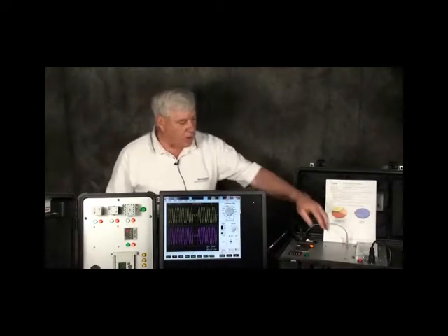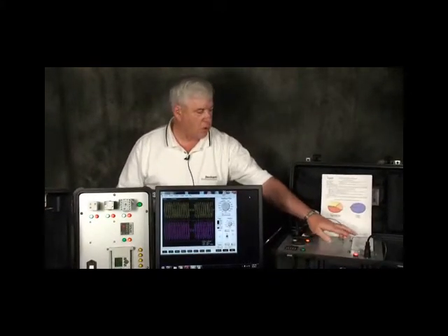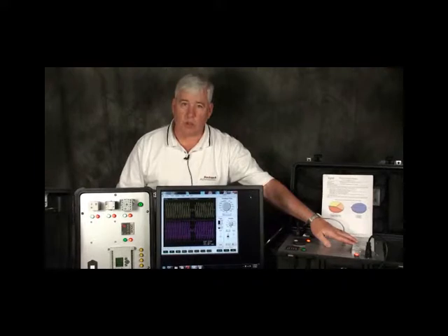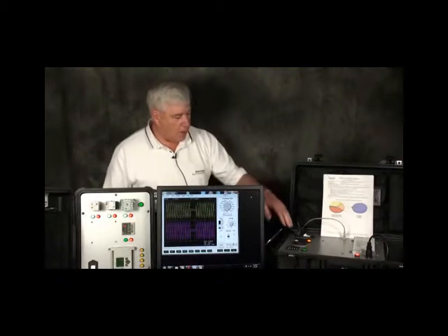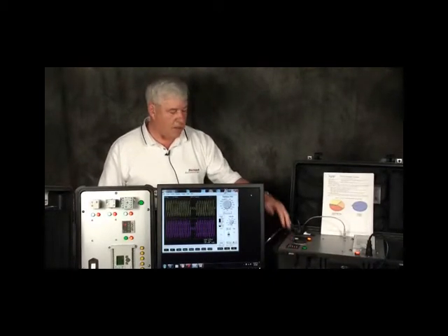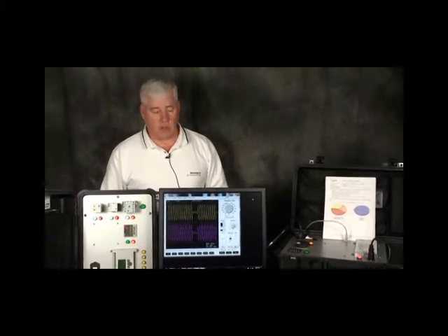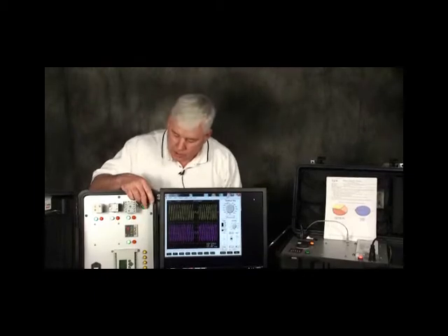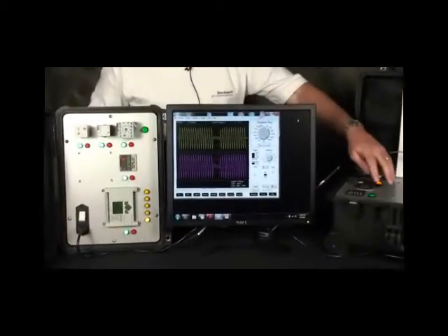So now we're back to our demonstration, and what I'm going to do is put in series with the load a dynamic sag corrector, or DySC. This is one of our mini DySC systems. This particular unit is a 2 amp system because we have a very small load here. I'm going to utilize the same settings we did for the very last sag we created, which you can see here on your monitor, that took down our entire system. Resetting the system so we have our program going again, and then once again recreating the sag.